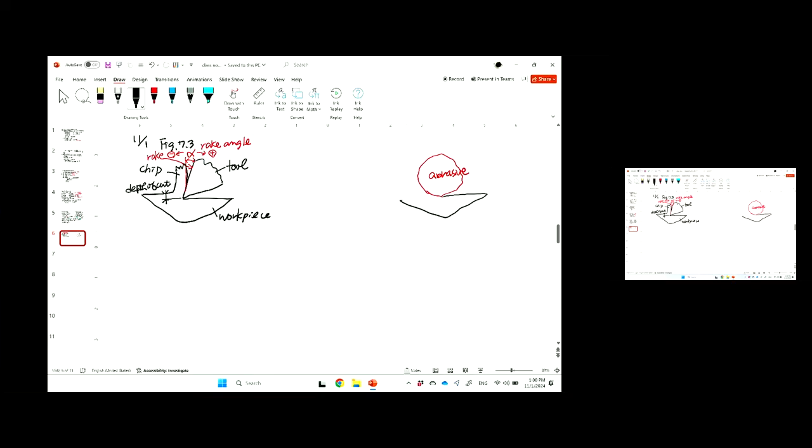Abrasive is tiny, right? Tiny depth of cut. So you don't even know like that. It's very tiny, and then the chip is created like that. So yes, you have tiny, tiny depth of cut. Let's put the depth of cut. So in this case, rake, super negative.